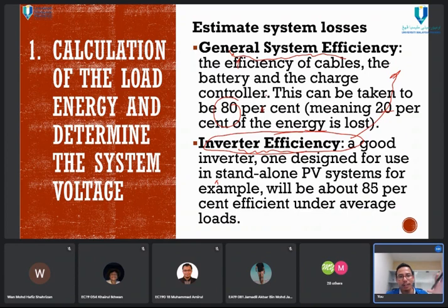Go to a battery shop or a tyre shop, or wherever they have a battery tester. Or if you have your own battery tester, you can check how much capacity is left. That battery test measures the capacity, the ampere hour, for example. But you can assume that if it is under the rated AH, it is half only. If you have a 40 AH battery, assume at least you have 20-something AH as the normal condition for the capacity. Or sometimes more than that. At least if it becomes half, it's okay, no problem.